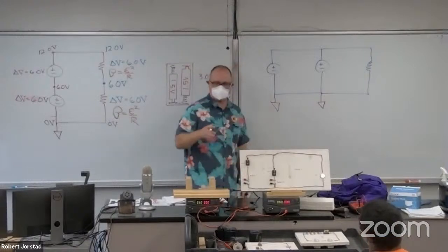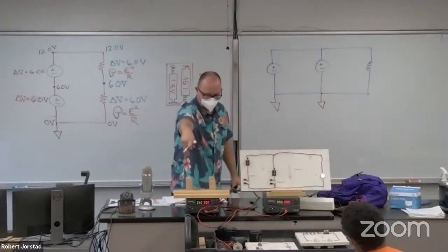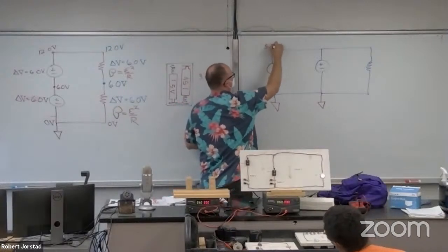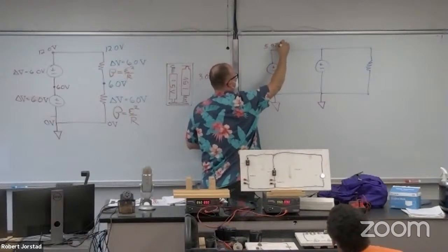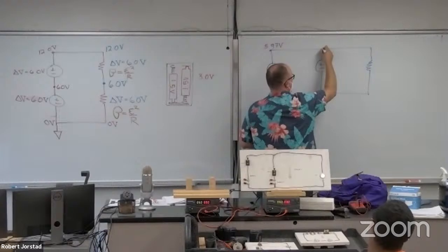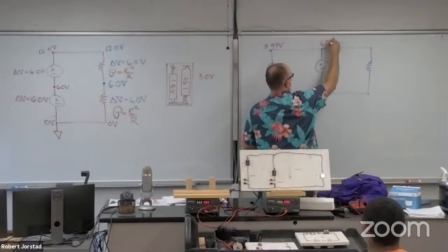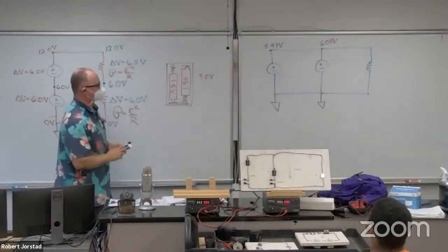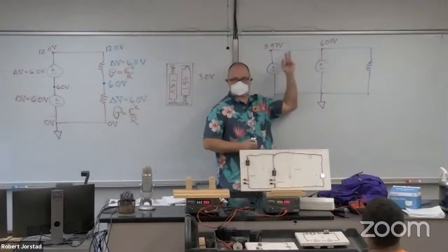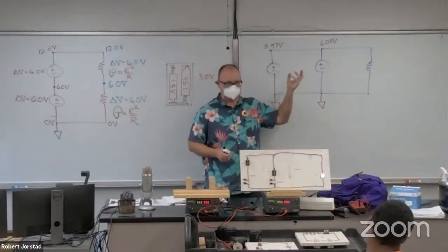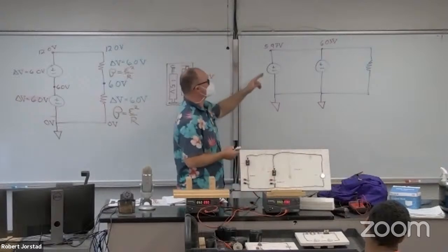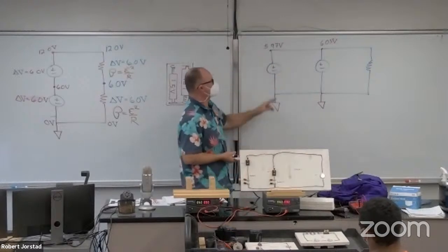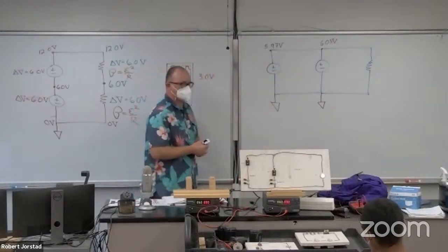Now, do you agree that these are only 2 sig figs, these 2 power supplies? Yep. So do you agree it might be possible that this one's at, say, like 5.97 volts? And this one might be at 6.03 volts, and we wouldn't know it? So the issue becomes, if these two aren't exactly at the same voltage, which we know they would never be, right? You can never get these dials perfectly. There's going to be a small dissimilarity here, and you could push current the wrong way through these loops. If I get them close enough, it should not be a big deal.